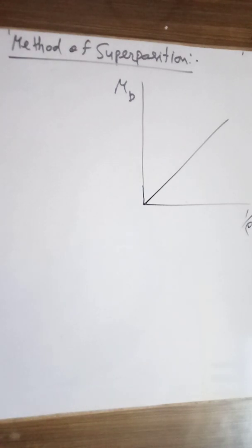then the effect of several loads acting simultaneously can be obtained by superimposing, by adding the effects of the individual loads. Or you can say the method of superposition permits us to use the known displacements and slopes for simple loads to obtain the deformations for more complicated loadings.